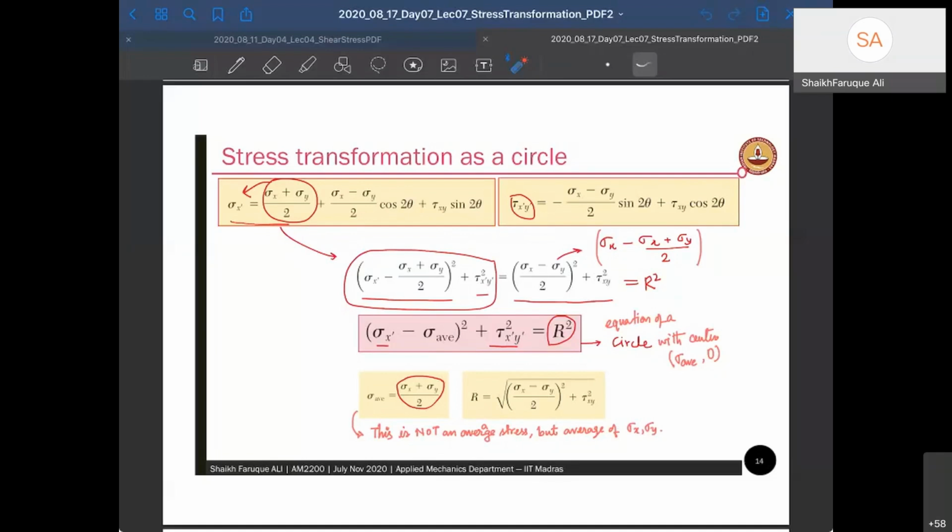And then we said that transformation of stresses is very, very important because the directions that you are looking at with the XY coordinates may not be the directions where you get maximum stresses, right? The system, the member, or the material can start failing from any other direction apart from your regular X and Y coordinates. Therefore, it becomes very important for an engineer to understand the values and directions of stresses along the 360-degree orientation of the material point, right? And for that, we need stress transformation.